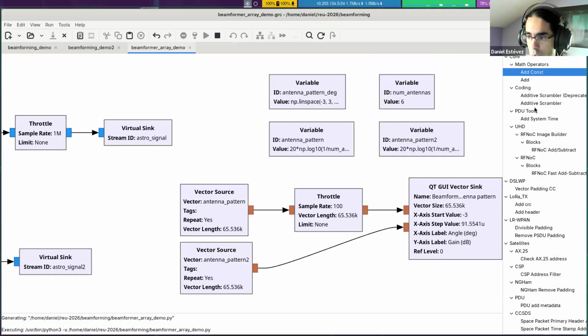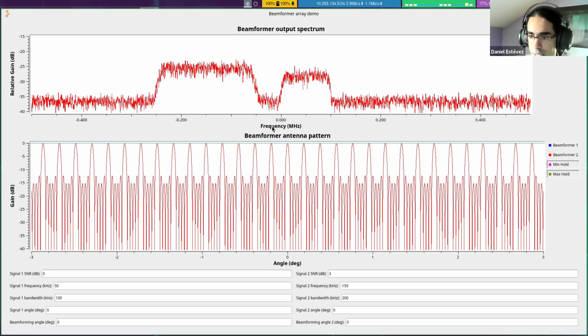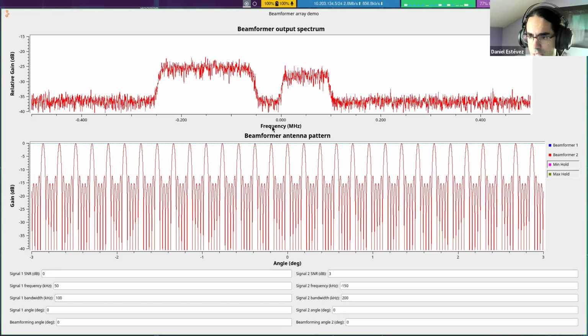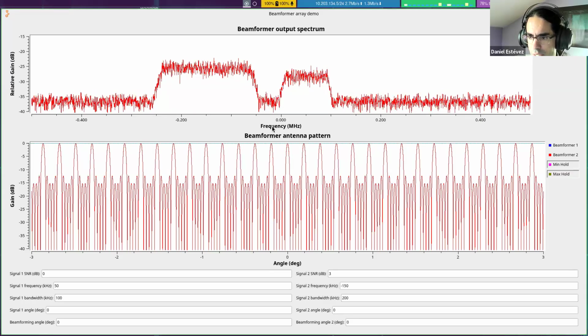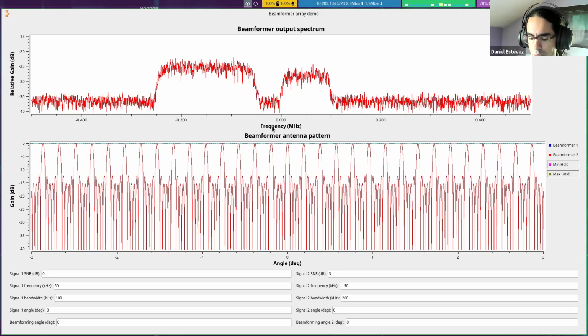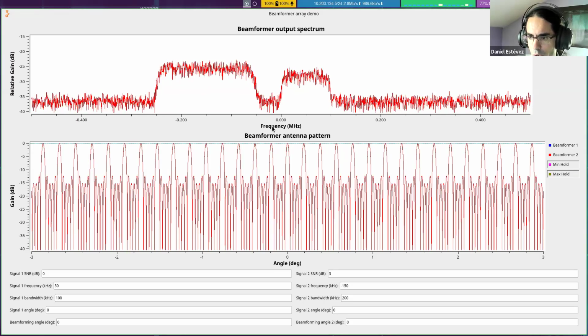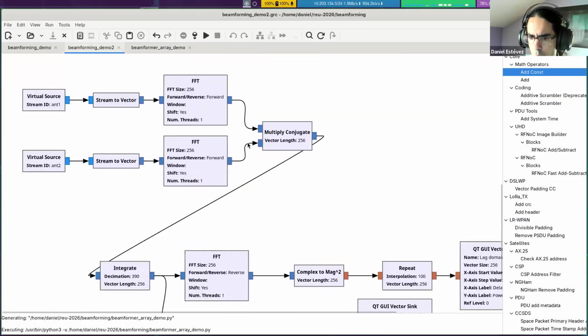And in fact, there is a way to perform all these calculations by doing Fourier transforms. That is essentially what imaging does, or the way that imaging is normally implemented. It's not built out in the naive way, which would be we have a beamformer and we sweep it over all the pixels in the sky. It's done more in this way.